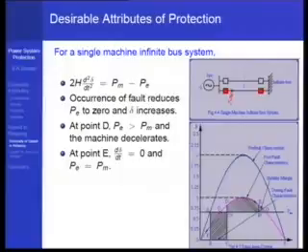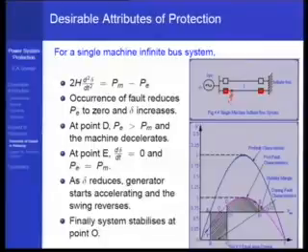Nobody designs a power system in which the protection system operating time, inclusive of circuit breaker operating time, is close to critical clearing time. But in a system where abnormal things are taking place, like lines getting tripped and cascade trippings, this critical clearing time may start reducing. So you need to worry about that also.